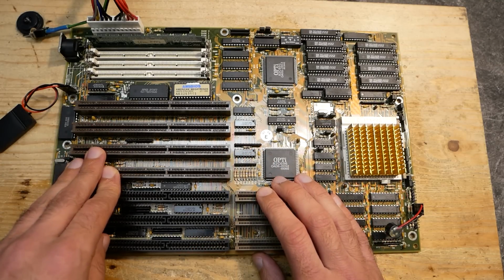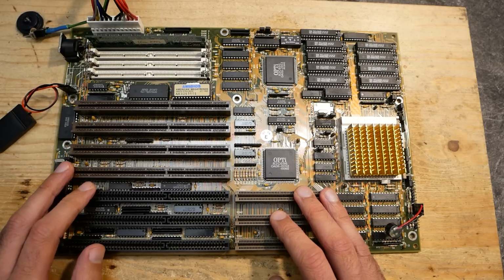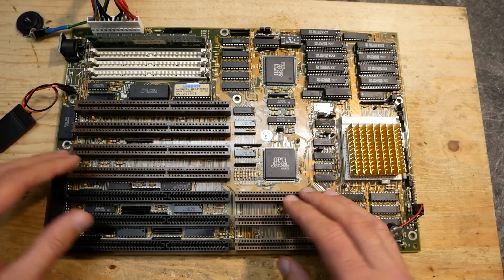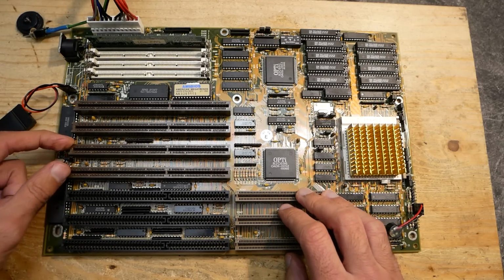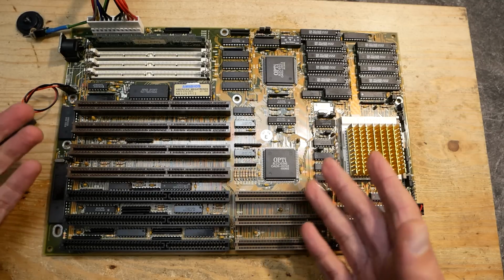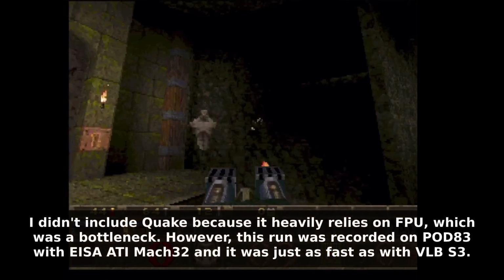In an ISA system, where bus mastering was not a thing, the bus would most probably get slower and slower under a heavy load with so many expansion cards. EISA, on the other hand, should scale much more efficiently in such cases, and the system would be more responsive even under a heavy load. At least this is what I think.